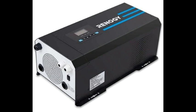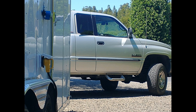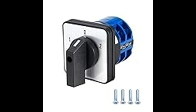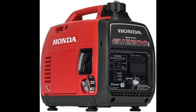In addition to having a battery-powered inverter provide your AC requirements, you may also want to use a backup fuel-powered generator. With a trailer or van, you also might want to take advantage of the grid, or shore power as it's called. When using shore power or a generator, you should use a transfer switch. Transfer switches are available in either manual or automatic. A transfer switch basically switches the source of your AC input power from your battery pack powered inverter to a fuel powered generator or shore power.